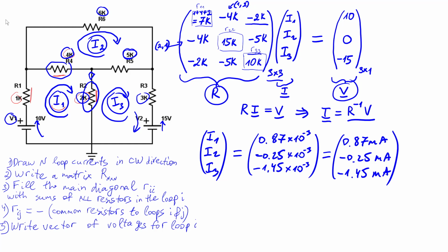So just take I1 minus I3 and you will get current through that resistor R2, and so on. So you can find basically voltages and currents on every single resistor. If you replace it with impedances, if you want to add capacitors or any other elements, you can do the same technique to find voltages and currents in the circuit.